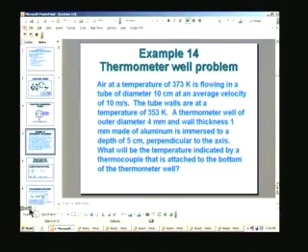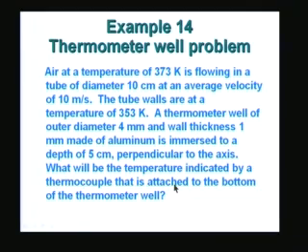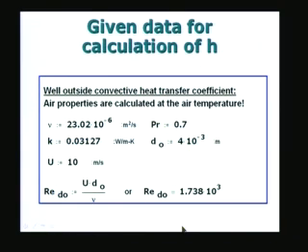details of the problem. So, we have to calculate the heat transfer coefficient on the outside, which is calculated based on the properties of the fluid and the velocity of the fluid which is given, the temperature and so on. So, what are the properties we require? We require to calculate the Reynolds number.